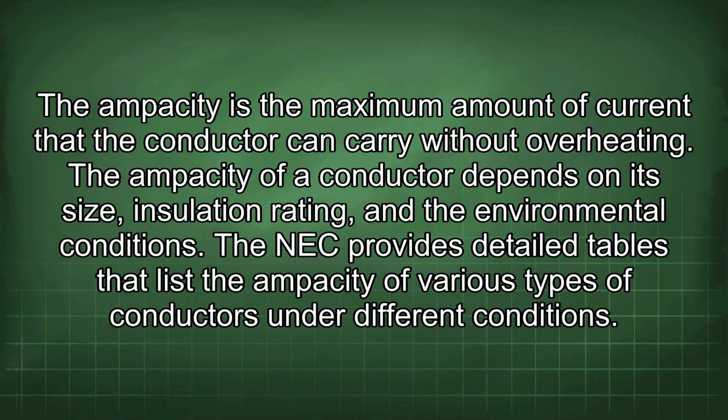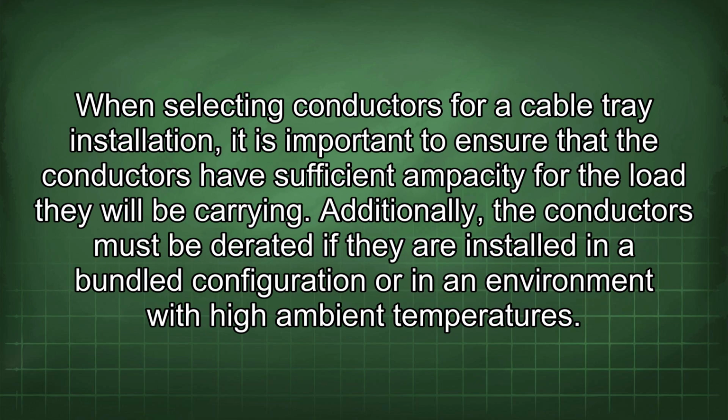Another important consideration is the ampacity of the conductors. The ampacity is the maximum amount of current that the conductor can carry without overheating. The ampacity of a conductor depends on its size, insulation rating, and the environmental conditions. The NEC provides detailed tables that list the ampacity of various types of conductors under different conditions. When selecting conductors for a cable tray installation, it is important to ensure that the conductors have sufficient ampacity for the load they will be carrying.